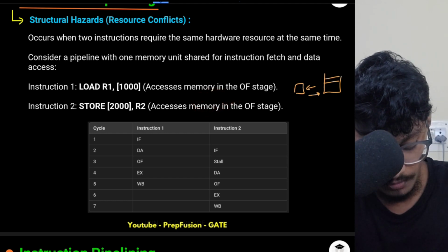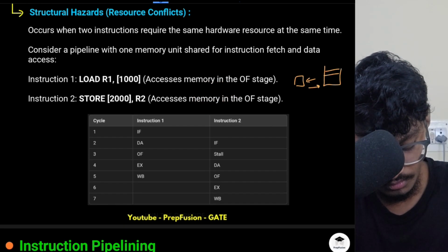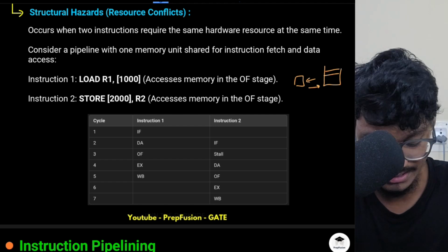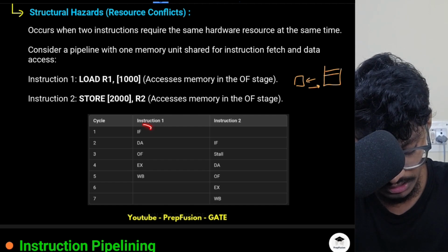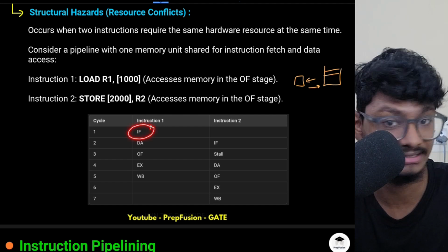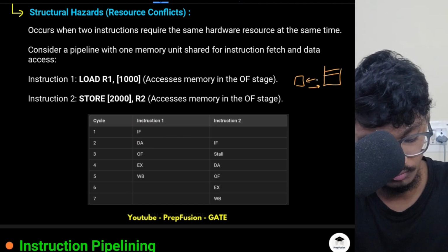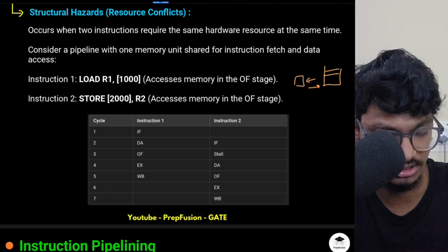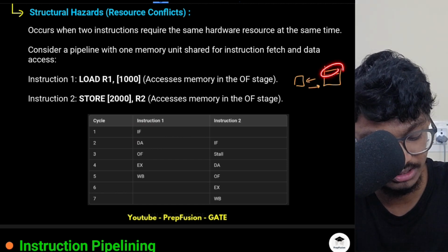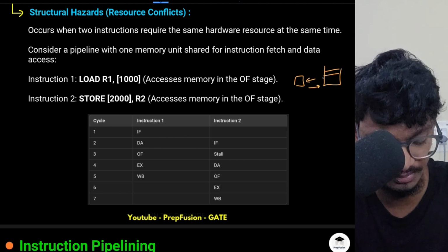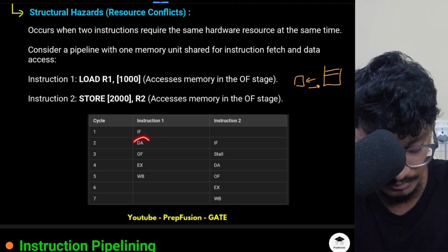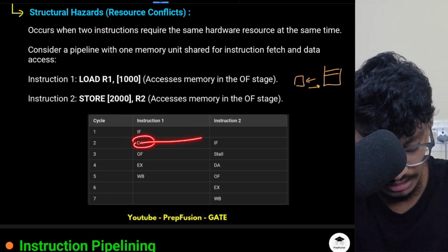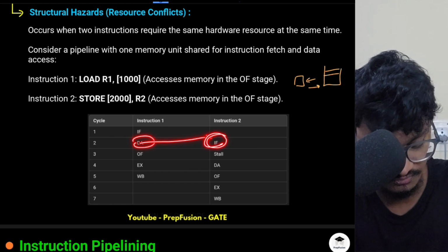Okay. What we can understand is that here I am doing instruction fetch, correct? This is also accessing the memory, because we have only a single bus, so the instruction is fetched from the memory location whose address is pointed to by the PC. Then I am decoding, and in this decode I am also doing instruction fetch.